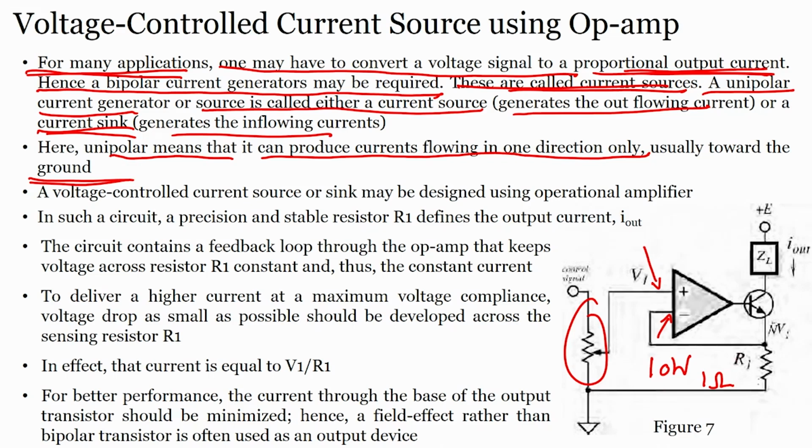So, when this happens, that means this transistor conducts, and the current across this resistor depends on the voltage we have applied over here, because it is trying to follow the same voltage. Depending on that, if you have your emitter current here, then the same current will be there in the collector.